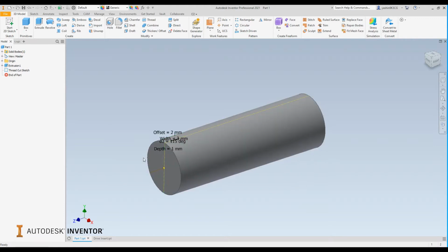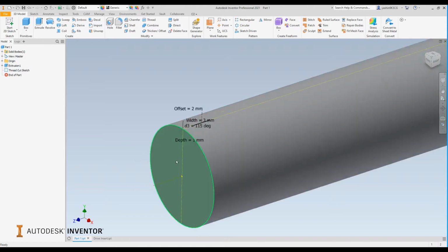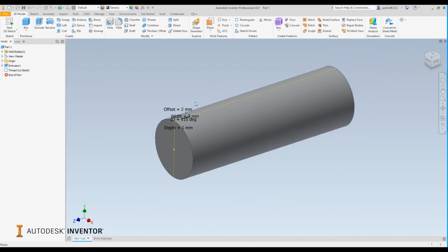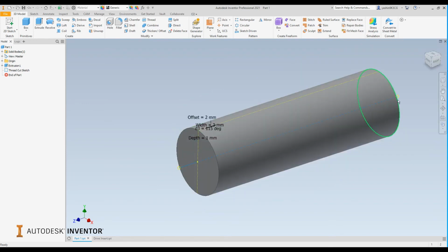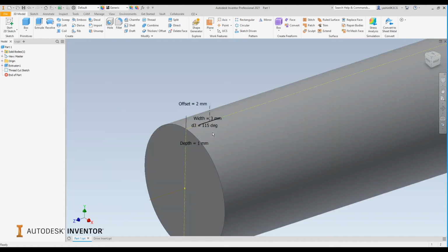So there are a couple of elements that you'll need before you actually run the coil. That will be a solid body or feature such as a stub, and a work axis. The work axis is going to define the direction of the coil. This can be a sketched entity too. Over and above that, you'll need a closed profile or a pitch profile. Okay, so thread profile, pardon.